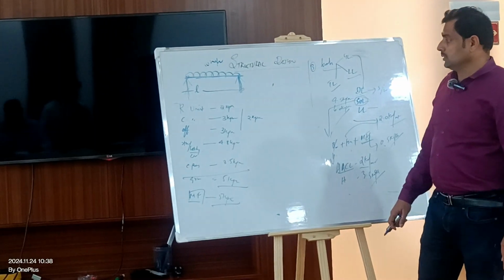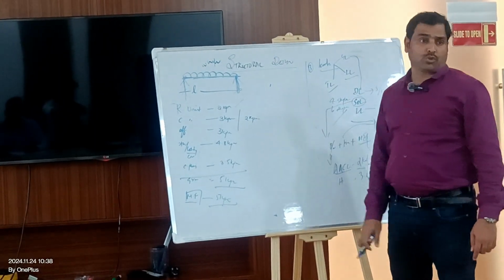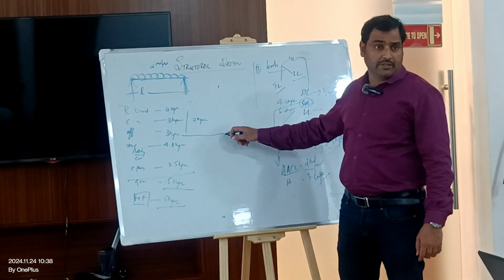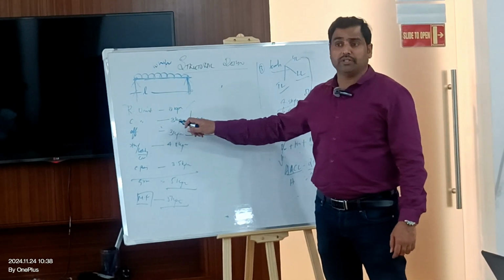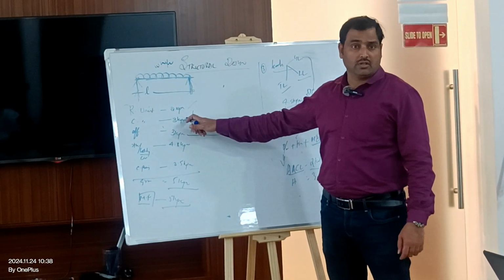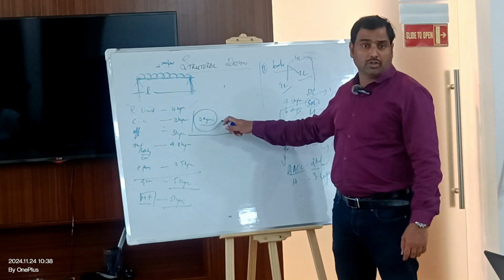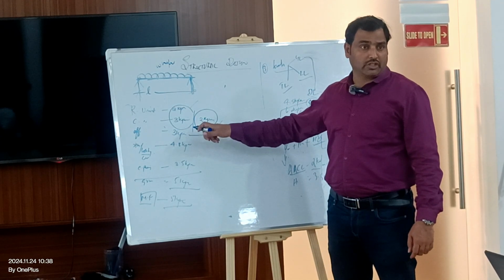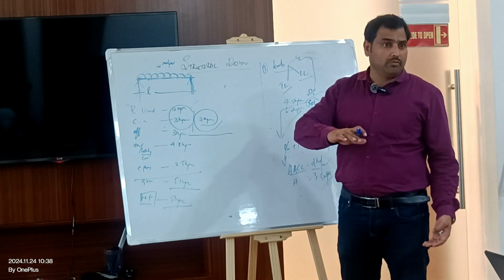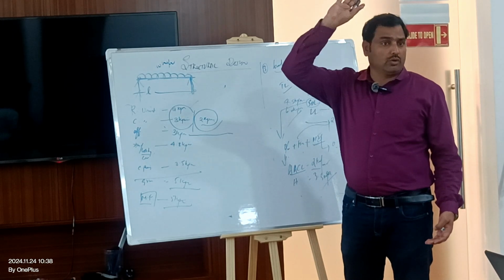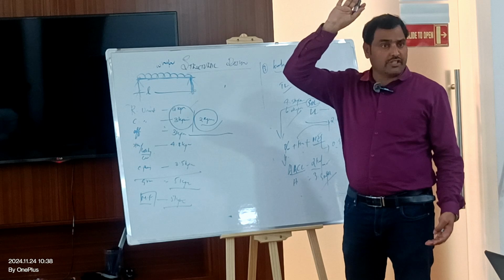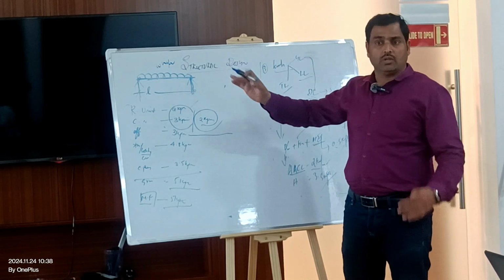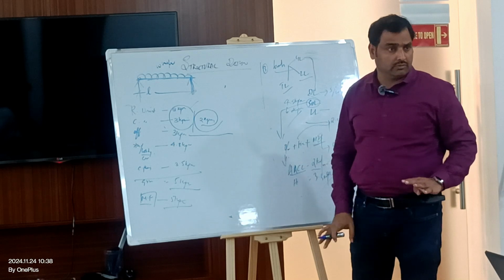For a residential building, it is 2 kPa. For an office building, it is 3 kPa. For a commercial building, it is a combination of residential plus offices. Wherever there is residential, follow 2. Wherever there are offices, follow 3. In a commercial building, the below 3 floors might be offices and the above 10 or 12 floors might be residential. So the upper floors will follow 2, and the lower 3 floors will follow 3.